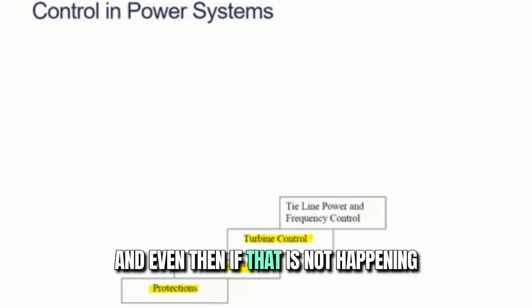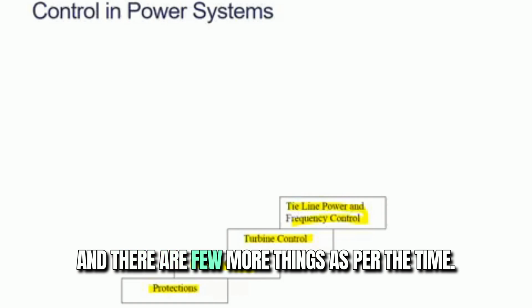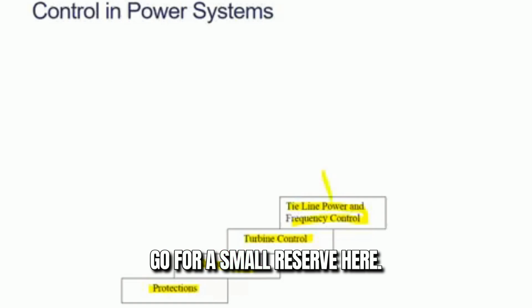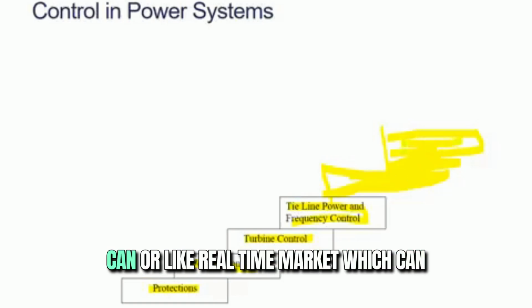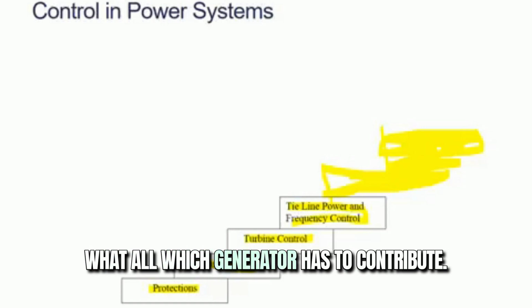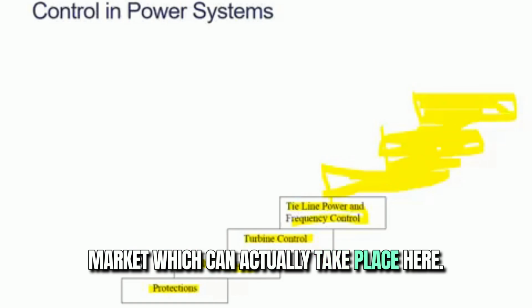And even then, if that is not happening, then we will go for tie line power for further controlling of the frequency. And there are a few more things as per the time. If time is more, then we can go for a small reserve. Then we can have a real-time market, which can help the power system economically decide which generator has to contribute. If you have more time, then you can have an intraday market.